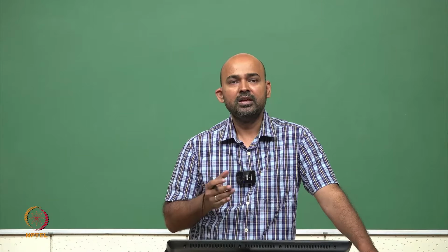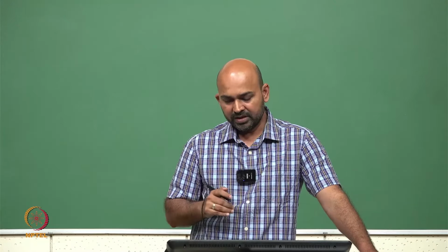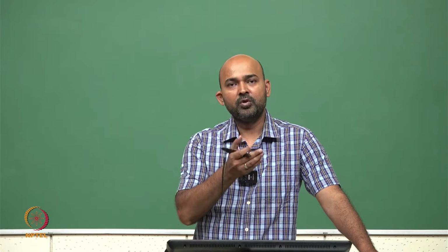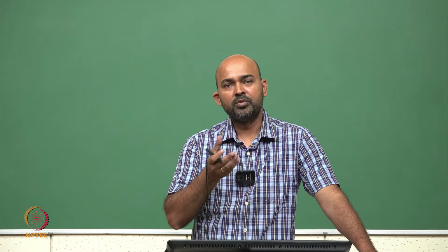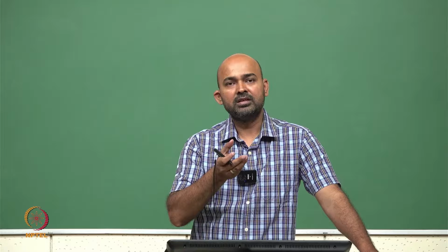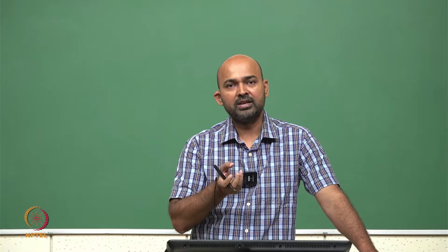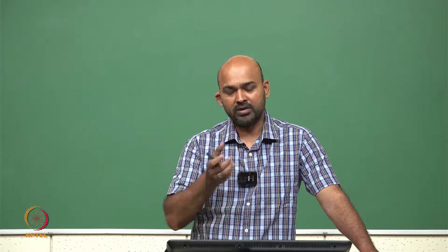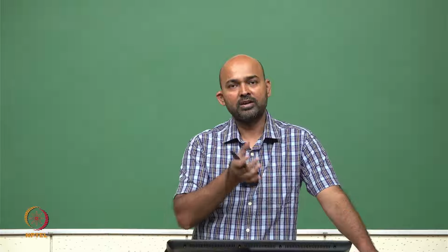These are four very important parameters: VIH, VIL, VOH, VOL. As the subscript says, VIH is the input high, the voltage at which input is going to be detected as high. VIL is the low voltage at the input, VOH is the high at the output, VOL is low at the output.